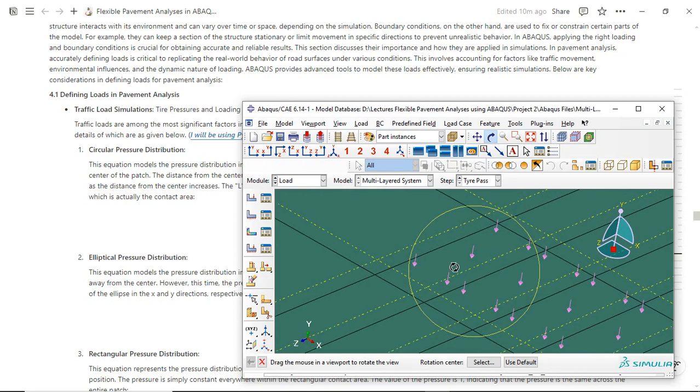If you have a poorly modeled tire patch, assuming a point load or a uniform pressure without knowing the reason behind the selection, it can overestimate the localized stresses at these regions and lead to unrealistic predictions of pavement damage. So if rutting and cracking are occurring, those unrealistic behaviors will be dominant here.